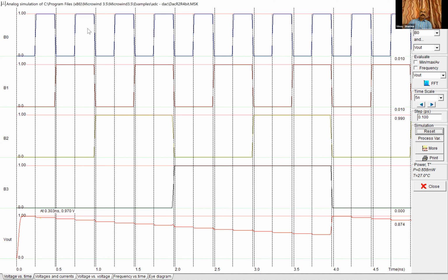And when you turn on the value 3, that is B1 and B0 both on, they will reduce 1/16 and 1/8 both from the output. So you can see the value comes down a little bit. As you keep turning on the NMOS combinations, the values keep coming down.